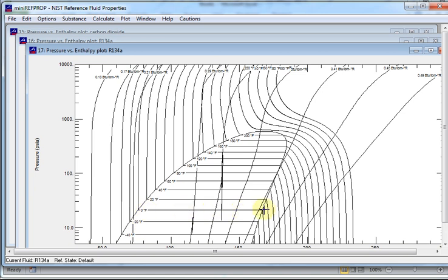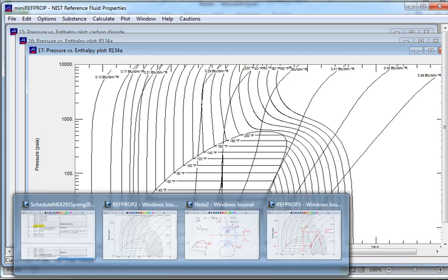So what we want to do is say, okay, it looks like the pressure is going to be about 20 psi. True? And what about if I'm rejecting it at, did I say 140? The high pressure, try to remember these numbers, is around 240 psi. That's a big difference, isn't it? A much bigger difference. So what is it again? 20 and 240. Let's go back to this Excel spreadsheet.